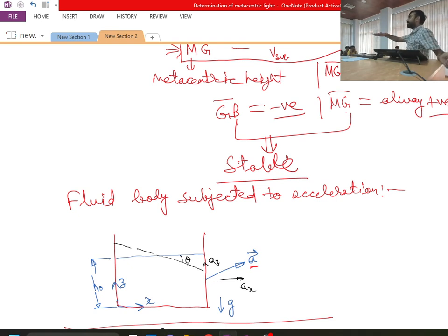Free surface is nothing but a liquid surface of constant pressure. Corresponding to this only we are having isobar. So I can say that when my pressure will be, free surface will be tilting like this. Any point I consider on this free surface, everywhere I will be having nothing but outside pressure P0. Whether I talk about this point, this point, or this point, along the free surface I will be having the existence of isobar.